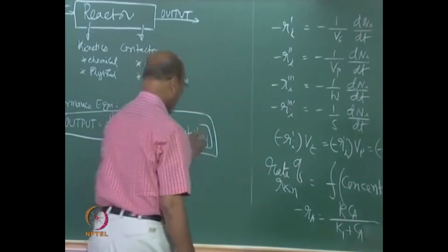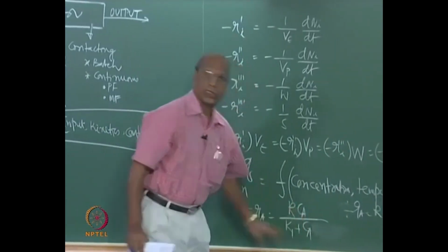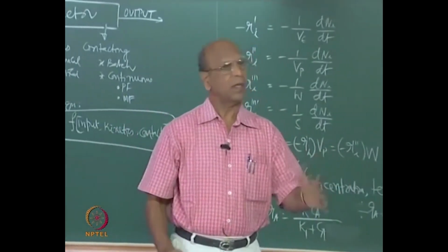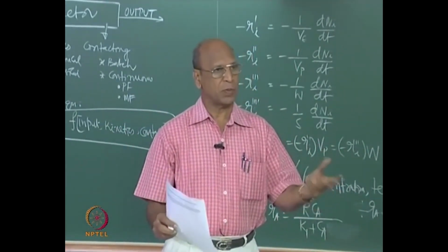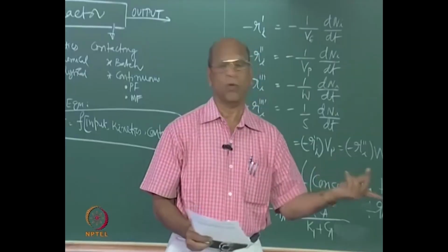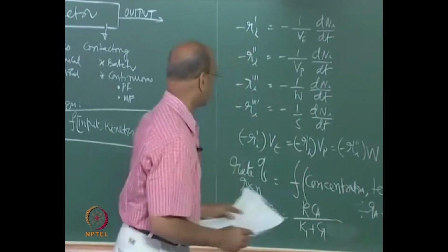That is why, whatever reaction rate you have here, somehow you have to introduce it in the reactor design expression, that is what we are going to derive, and then integrate that. Sometimes it is possible to integrate analytically, sometimes it is not, so you have to go for graphical or numerical integration, and then finally calculate either volume if conversion is known, or conversion if volume is known. That is the entire reactor design. Good.